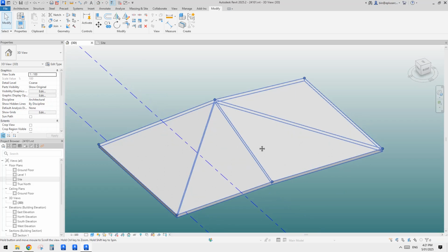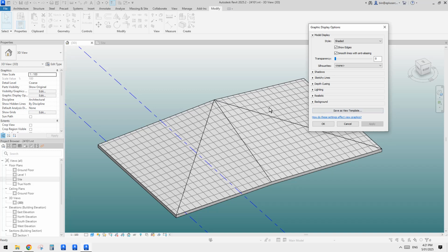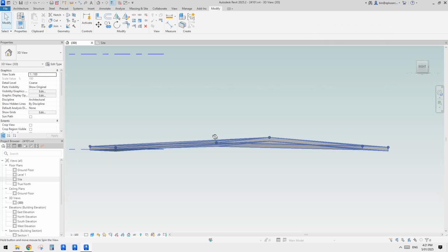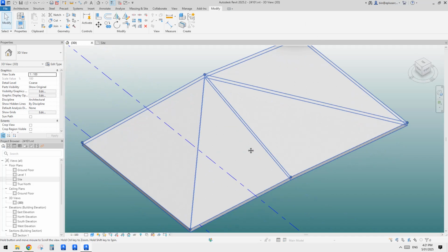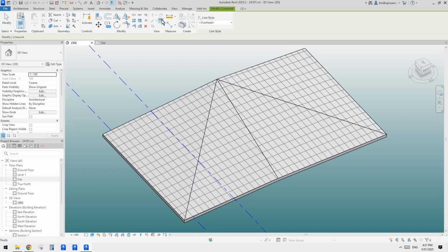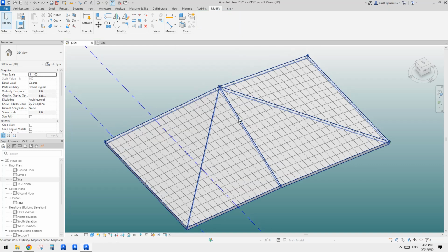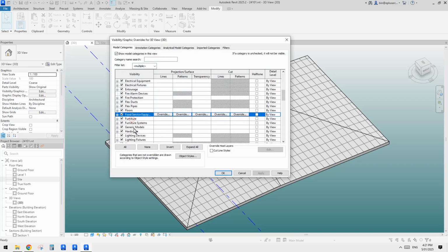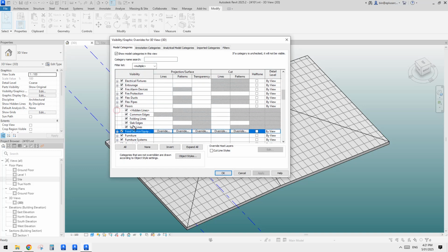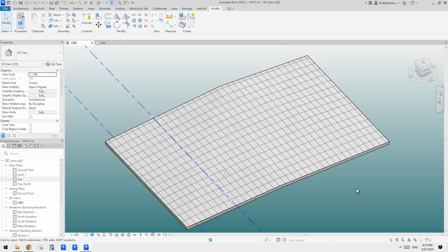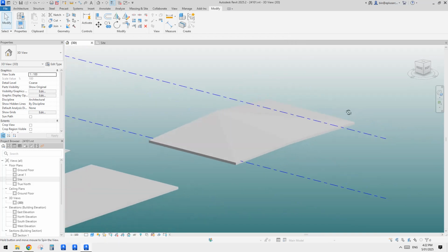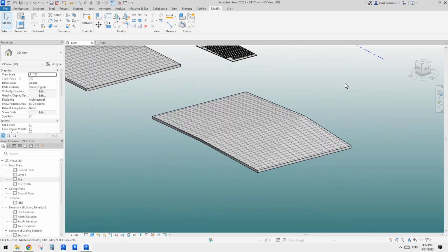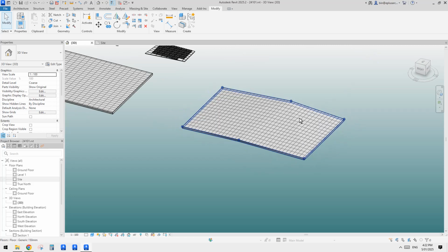And finally, we can see there's a different height, but can we just hide those lines? Yes, you can do this. Just use line work to manually hide them, or you can go to VV and go on the floor, and just untick the split line, so you can hide them. It's easier if you have more than, you know, like 3 in this case.